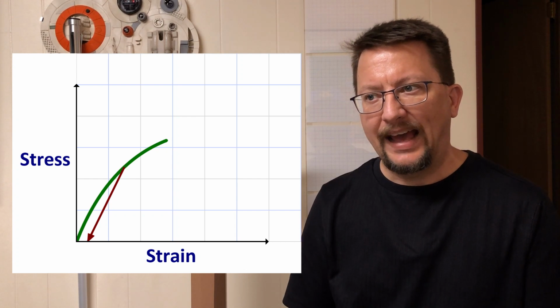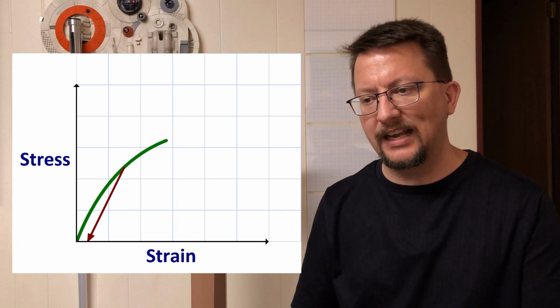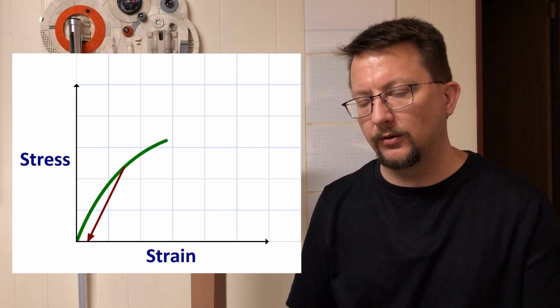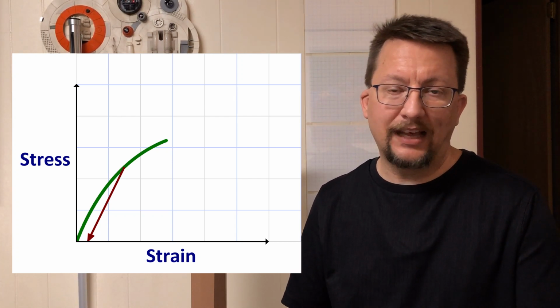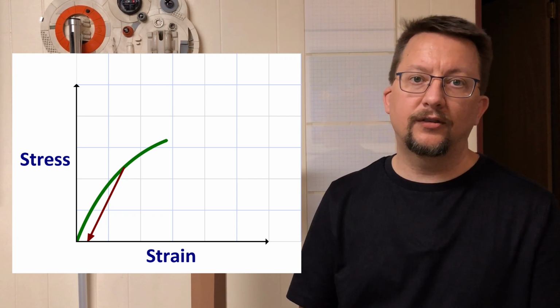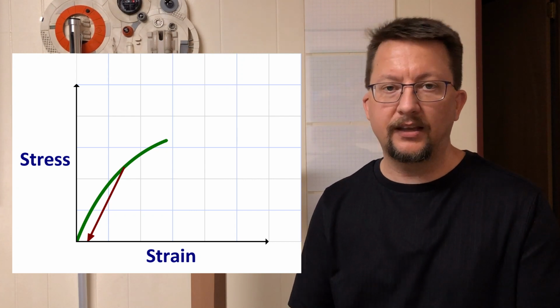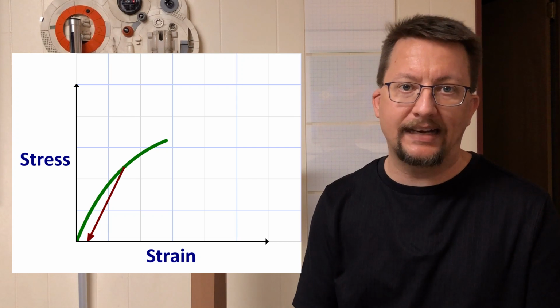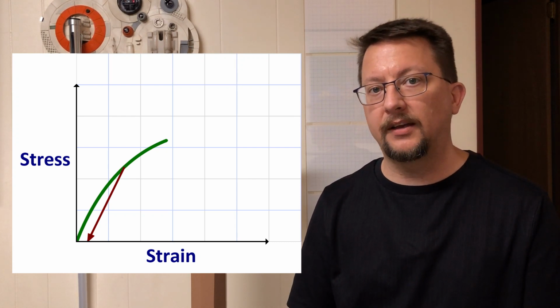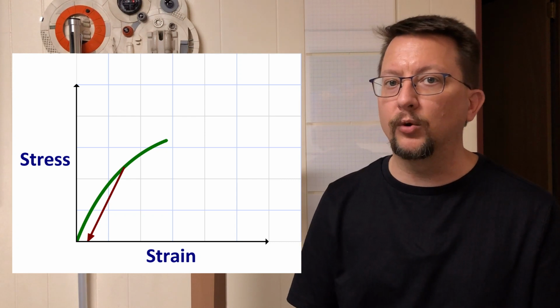So if you look at that curve, hopefully you'll be able to identify down at the base of the curve some sort of straight, short elastic region. And you pick that as your slope, and then you follow the curve up to the point where you're going to study it. And as you take that stress off, then you use that original slope and you come back down to the strain line, and that is your offset. That is the amount that you've permanently deformed your sample, which is important for us to know how well the material will hold, and if there is some sort of offset, what is that? And we can compare resin to resin and we can see what that is.